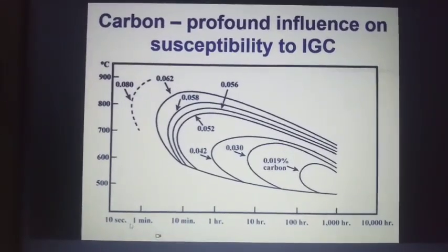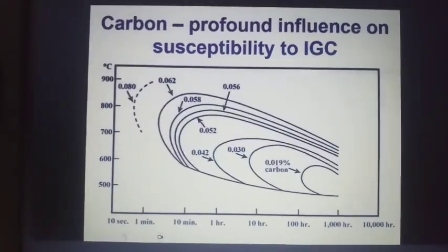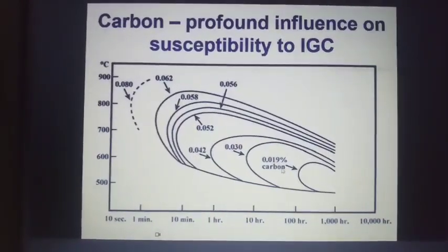That's why all the filler metal, all the things, when weldability is involved, all the base material and filler metal are chosen with L grade. This is the reason.